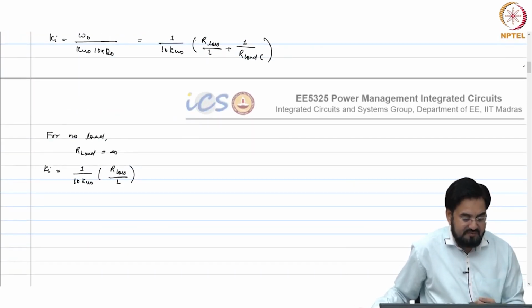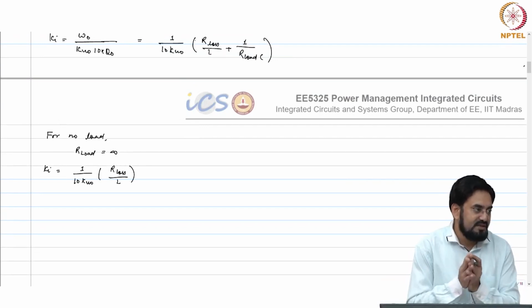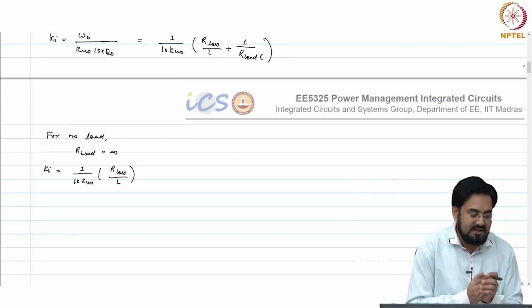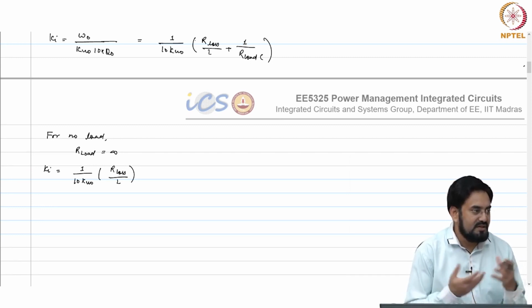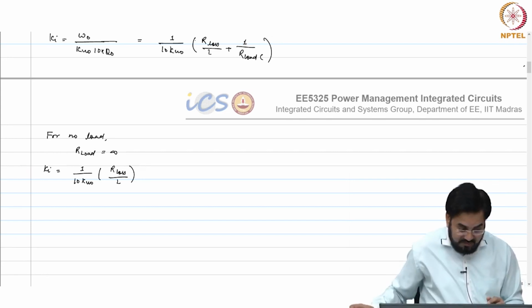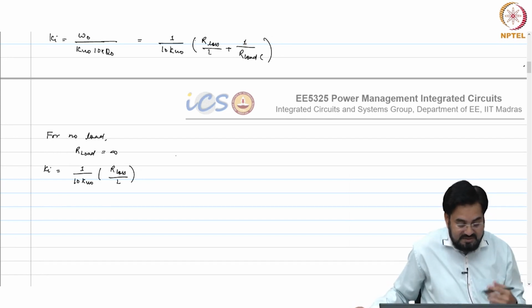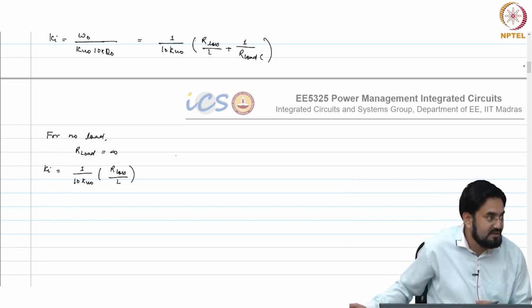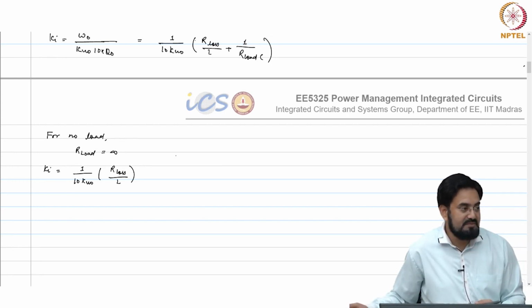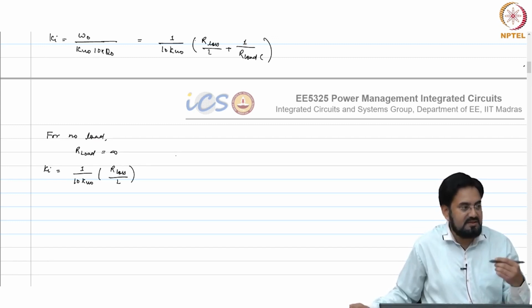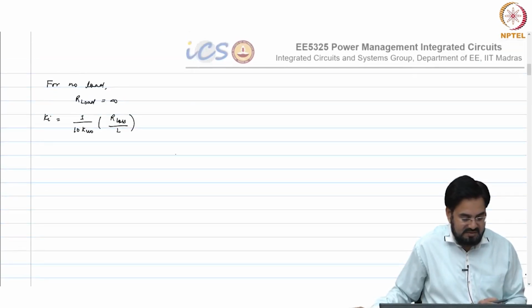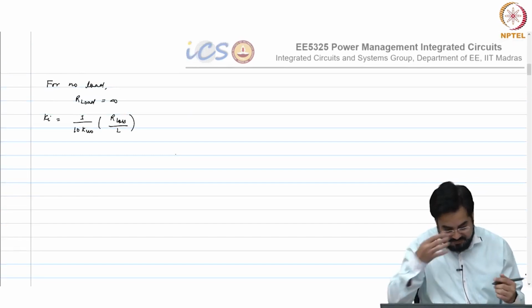So, once you find that, you can replace each and every block with its equivalent circuit, and you can run your transient simulation with PWM clock. But if you directly go to a sample system, then it will be very hard to analyze this in terms of stability. So you always design in continuous time and then convert into a sample system or switching system.